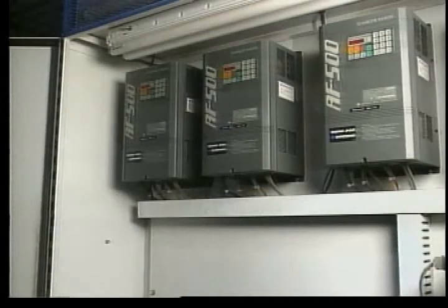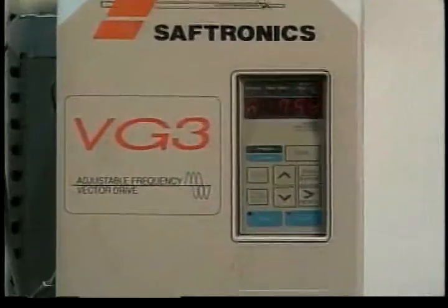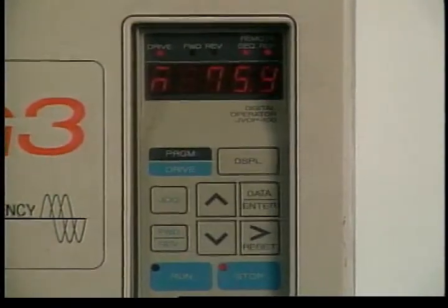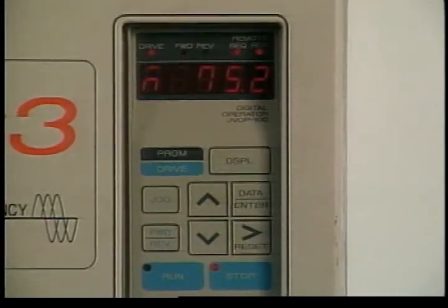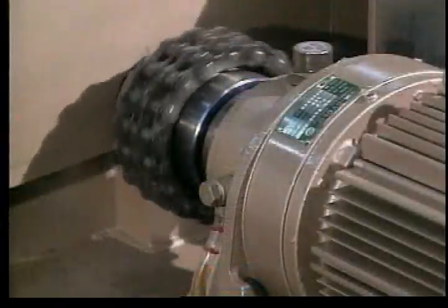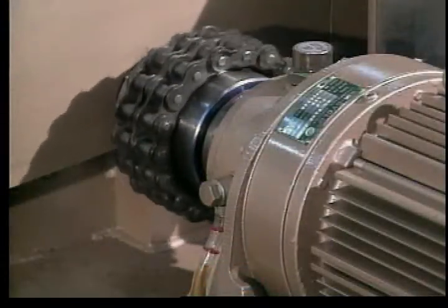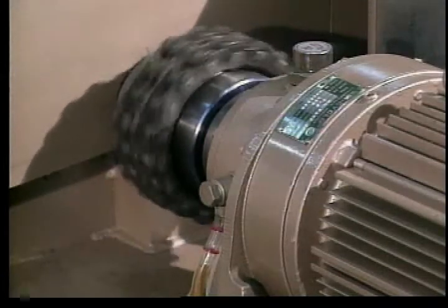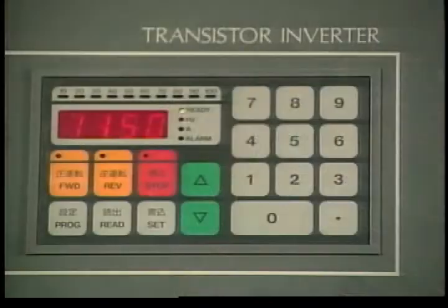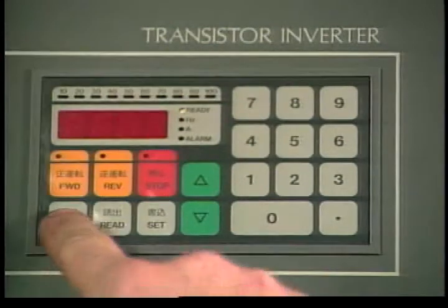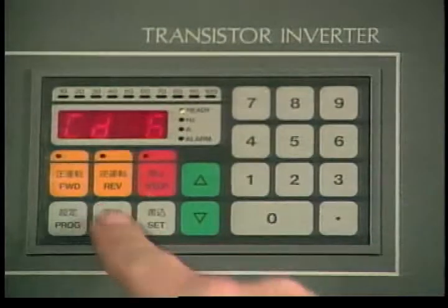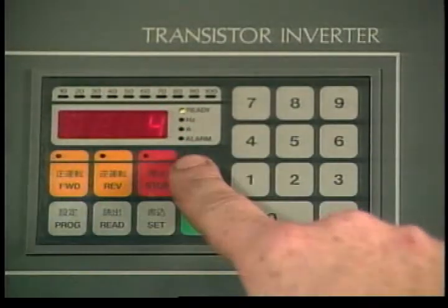These inverters can maintain reduced voltage and frequency indefinitely, and they can also provide control of much more complicated operations, such as maintaining speed and torque when loads vary unpredictably, providing precision control of speed when necessary, and regulating the power output of a motor. Typically, this type of inverter has a microprocessor through which the user can control all the different functions by entering instructions from a keypad or a control panel.